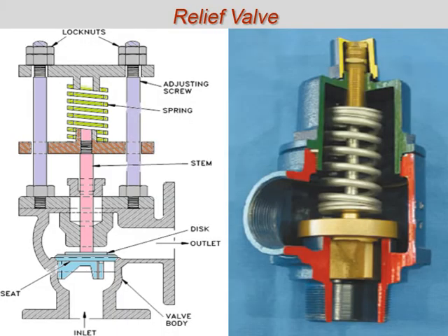Relief valves and safety valves prevent equipment damage by relieving accidental overpressurization of fluid systems. Relief valves are used on non-compressible liquids such as water, oil, etc. A relief valve gradually opens as the inlet pressure increases above the set point pressure, and it only opens as much as necessary to relieve the overpressure condition. This minimizes the amount of liquid lost. System pressure is felt on the underside of the disc.